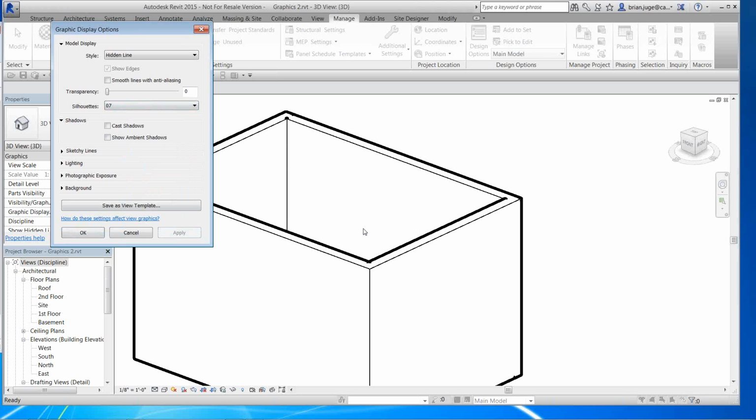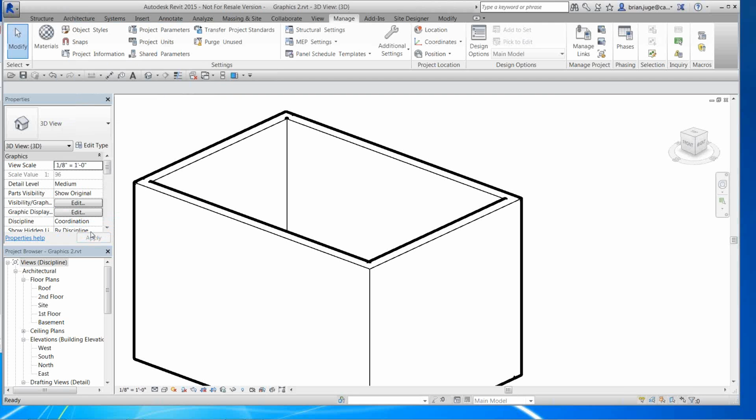What are we looking at? We're looking at outside corners, right? Drafting in 3D 101: outside corners should have a heavier line weight. Inside corners are a lighter line weight. And this is a pretty good example of that right here. Now if we're seeing something that doesn't look right, we can go in and change that and make a bigger difference on it. So I'm going to show you how we can do that. The first pass, I might pump up my drawing just like this, just to give it some different quality.